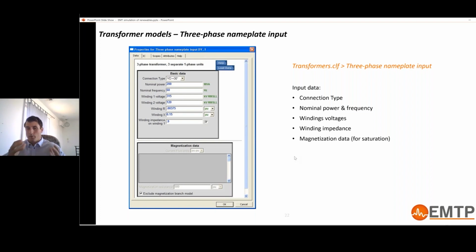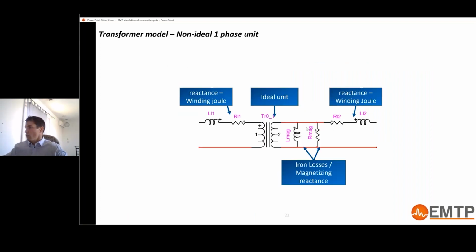When the transformer is in open circuit, manufacturers will apply a voltage, 1 per unit, 1.05, 1.1, and measure the current in RMS. And there exists a routine to go from this RMS value to instantaneous current flux for this nonlinear inductance. We have the exact same routine in EMTP. You can use it. This routine in the current version works for YY transformer. And so for Y delta, you have some extra manipulation to do. We will do that during the lab in order to better fit the result when you have a delta.